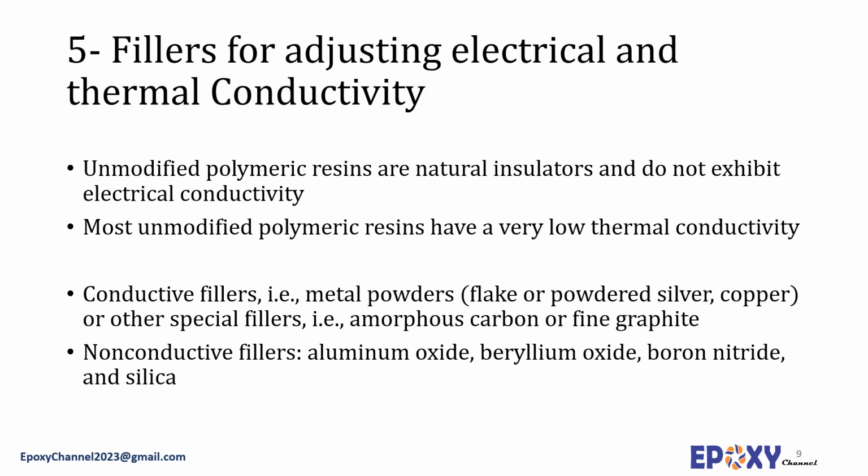Some applications, however, must conduct heat but not electricity. In these applications, the adhesive must permit high transfer of heat plus a degree of electrical insulation. Fillers used for achieving thermal conductivity alone include aluminum oxide, beryllium oxide, boron nitride, and silicate. Theoretically, boron nitride is an optimum filler for thermally conductive adhesives. Beryllium oxide is high in cost and its thermal conductivity drops drastically when it is mixed with epoxy resins.